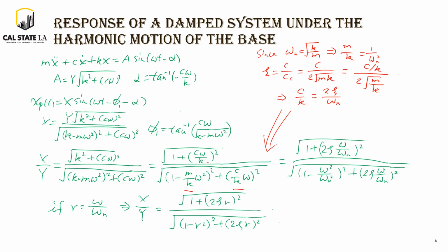Professor? Yes. Does it matter if the base moves in the same direction as x or in the opposite direction? So if y moves in the other direction, basically, right? It doesn't really matter that much. If you think about y moving in another direction, you can assume that y has a phase angle of 180 degrees, which basically means the sign of y is flipped. I see. Thank you. That's a good question. Thank you.